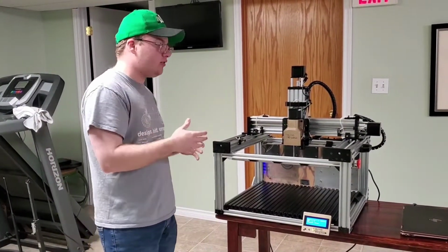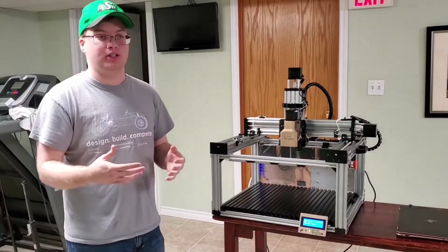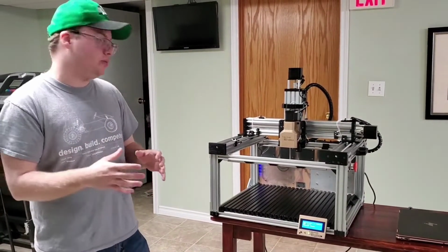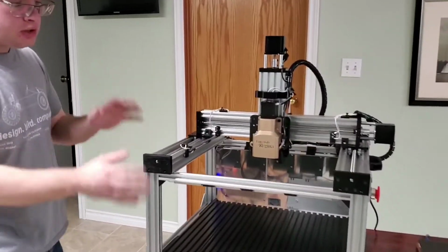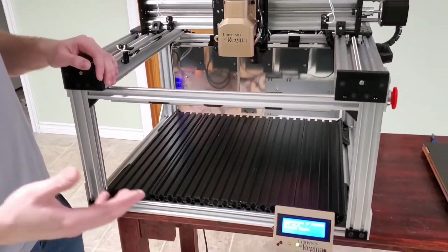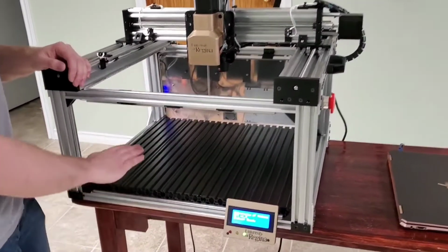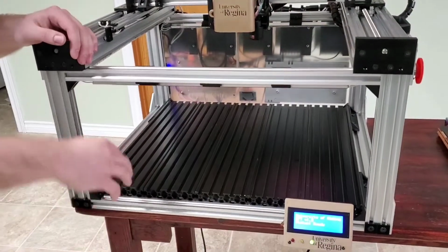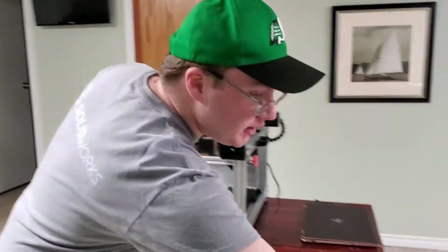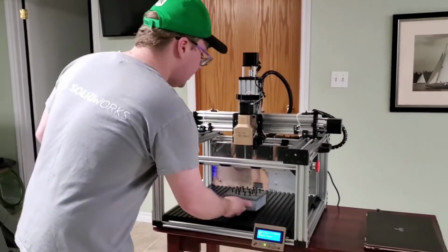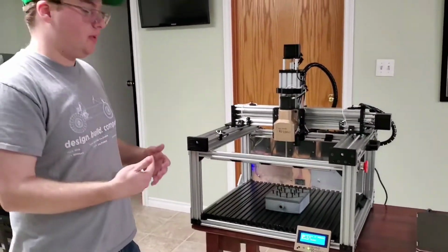Now there's about 25 plus unique 3D printed parts on the machine, and over 90 3D printed parts total on the machine. So if you come a little closer here, start at the front. Basically the mechanical system consists of 5 different elements. The first is the bed and frame. So the bed and frame is essential for obviously putting our filter down, like this one for instance, setting it down, and then having some means of clamping it down.